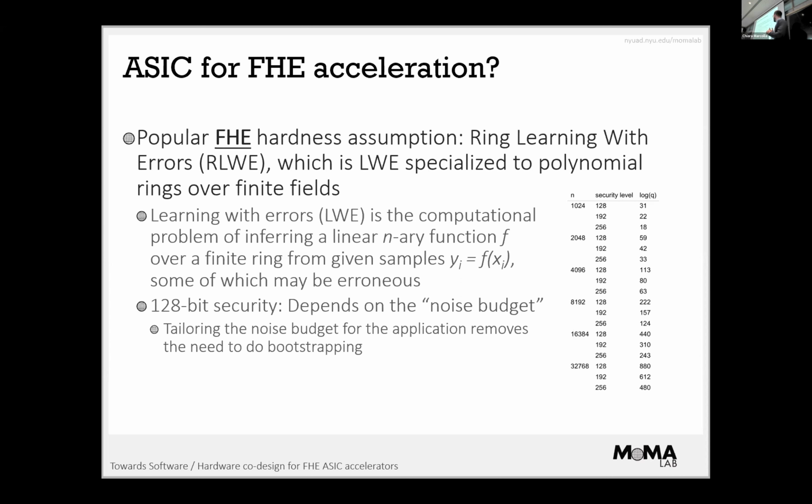So here we're talking about essentially trying to create hardware to compute very, very big polynomials. And again, there are two problems. One, we have polynomials. And the second, the native word sizes we have, they're not native to the computer. The computer computes 64 bits easily, but 128 to 256, it has to do magic, right? Because it doesn't fit in a register. So to be able to do more than 64, you have to introduce GMP, or some library to compute on things more than 64 bits natively.